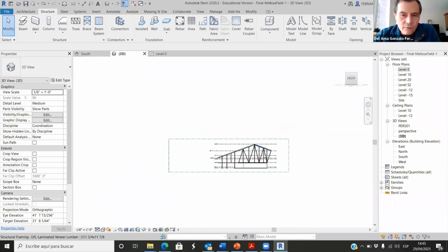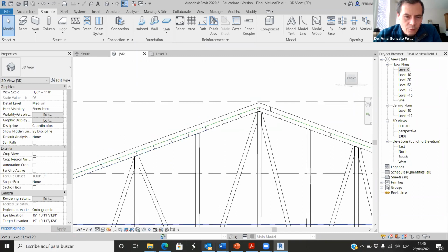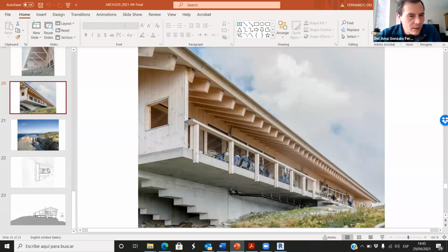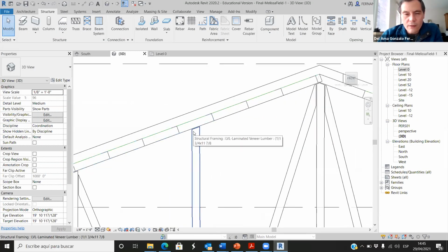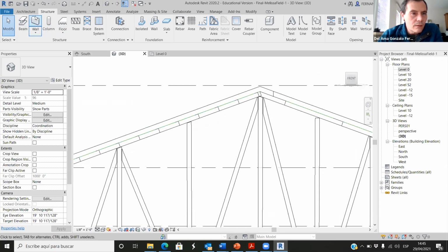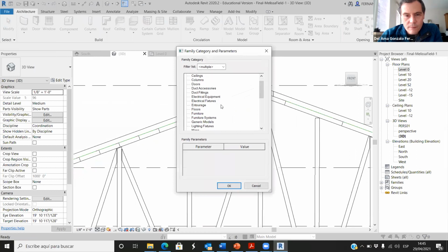And looking at the front view, you know that we have the roof. This is the roof. This is the beam system. Now the structural elements are, I don't know if we, yeah, so the structural element, this big structural element is just below the beam system. So now we can create those beams using architecture component. Model in place, it has to be something like structural framing as well.